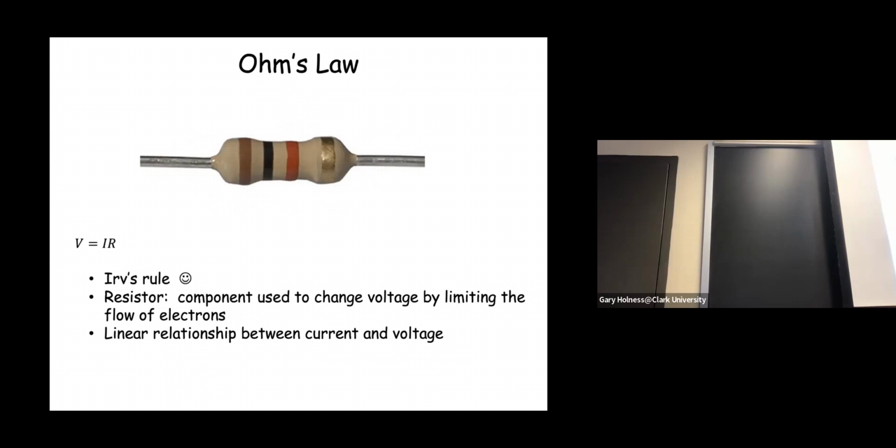And in the circuit we're going to build on Friday, we do exactly that with a 220 ohm resistor, because that's how you protect an LED from burning out and also protect the digital I/O pin on the Arduino from being burned out. Okay? All right. Any questions about this? No questions? Make sense? Yeah? All right.